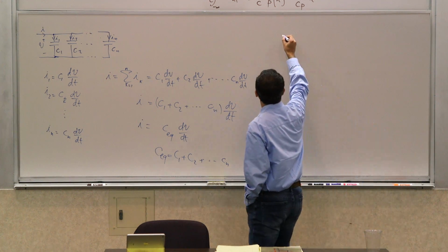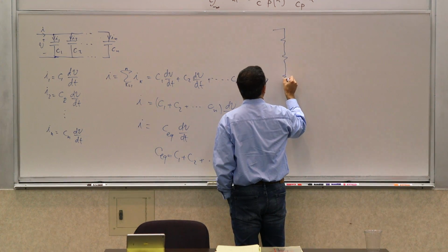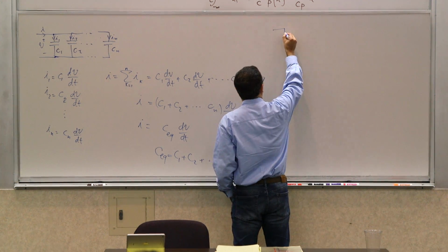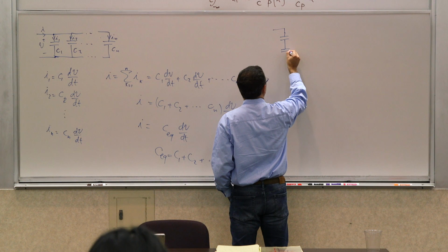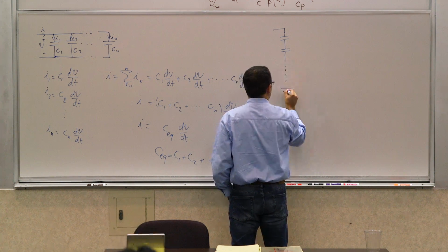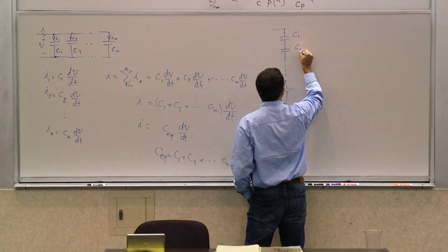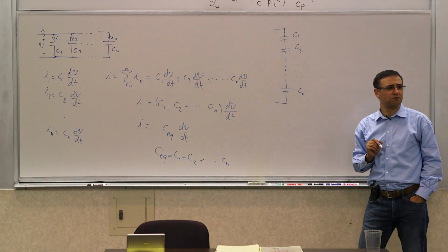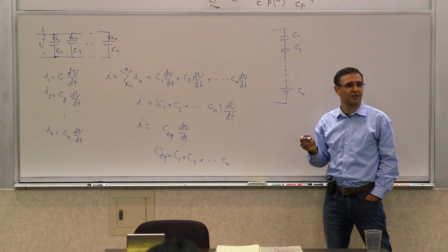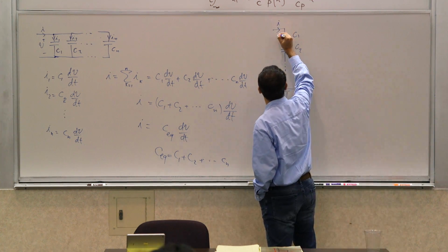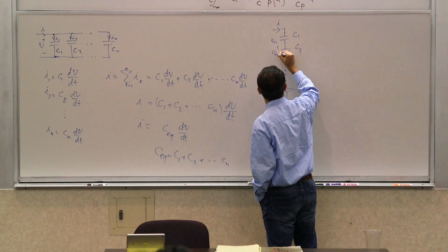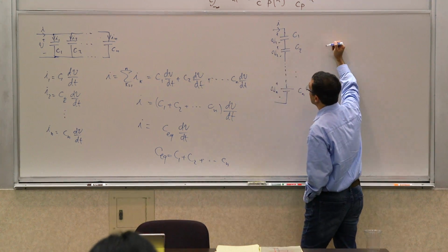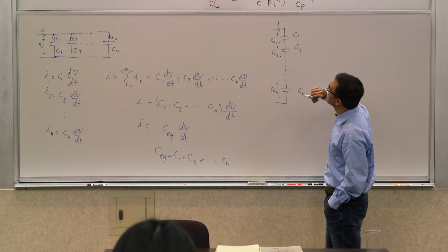And if you put them in series, again, this is nothing earth-shattering. I talk about resistors, I draw a resistor. So you have C1, C2, and Cn. So what is common now among these? What do they share? The current, right? So all of the currents are I. So this is V1, V2, and so on and so forth, Vn here. So if their currents are shared, then I use the second equation, the integral form.